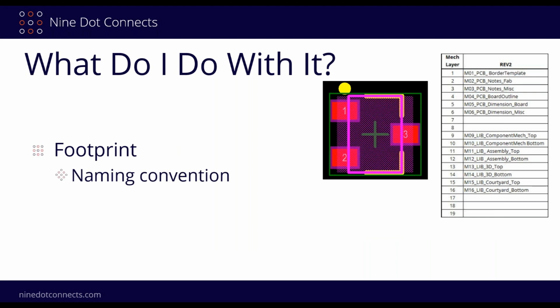So also footprints, I didn't put it here, but naming convention is really important. And by the way, I would encourage everybody to use the IPC naming convention. You can find it on the web. They don't charge you for it, which is kind of rare for them. Normally they charge for their standards, but the footprint standards are available on the web free of charge.